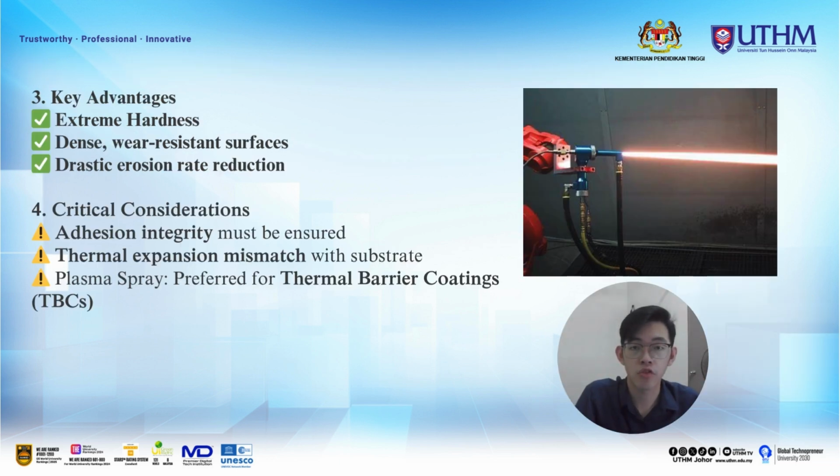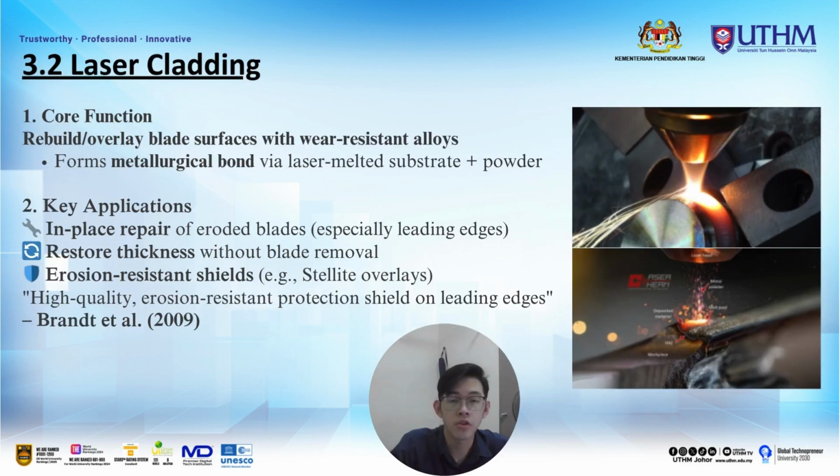So the advantages of HVOF are extreme hardness, a dense, wear-resistant surface, and drastic erosion rate reduction. Critical considerations include that adhesion integrity must be ensured, and thermal expansion mismatch with the substrate. The plasma spray is preferred for thermal barrier coatings, TBCs.